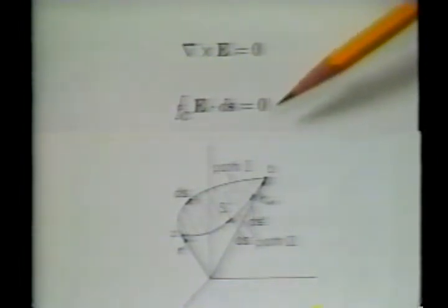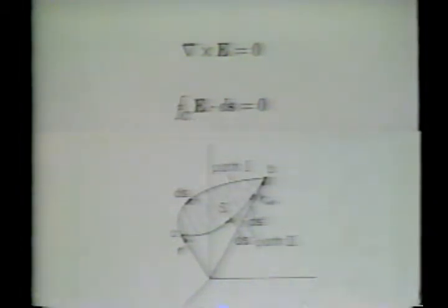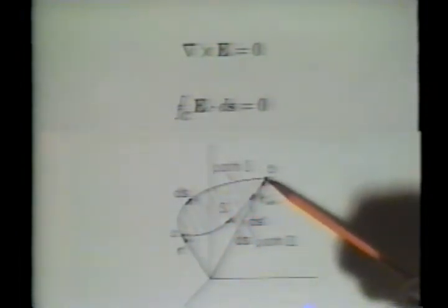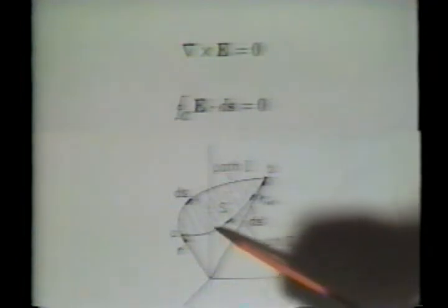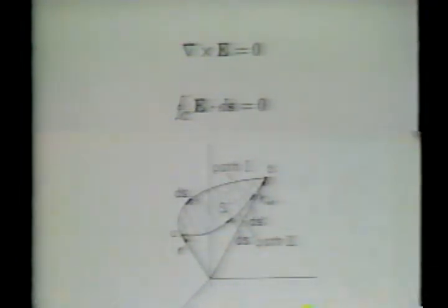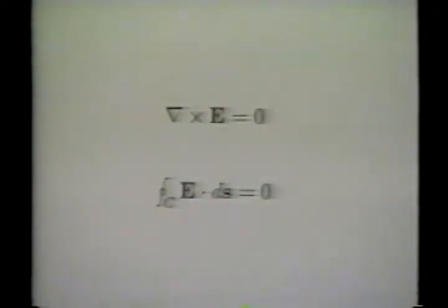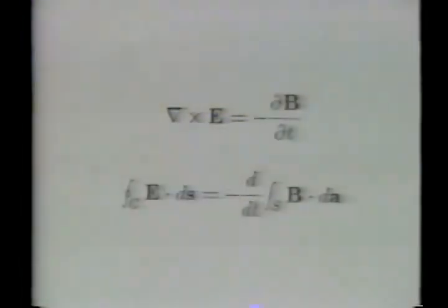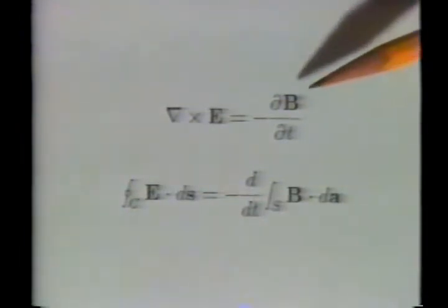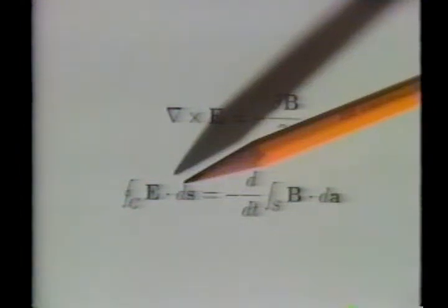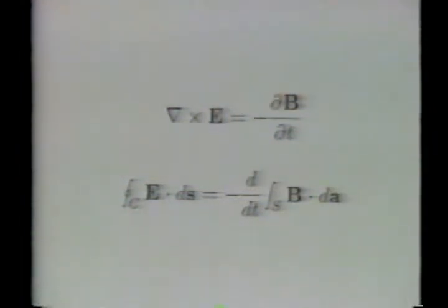This experiment emphasizes this by showing how the voltages measured by these leads and the oscilloscope are path dependent. Here's the ground lead of the oscilloscope. Here's the top trace lead, and connected to the same point is this bottom trace lead. A magnetic flux is created in a toroidal magnetizable core by driving this winding with a sinusoidal current.